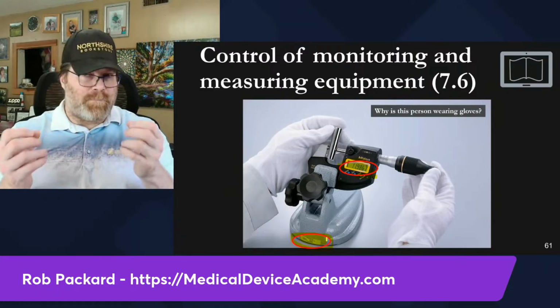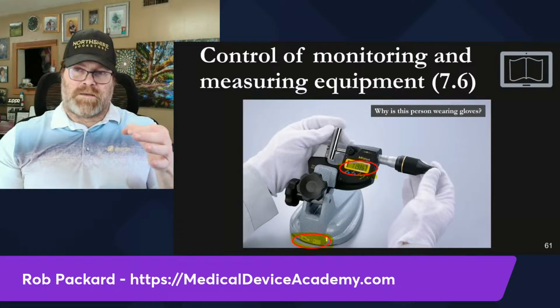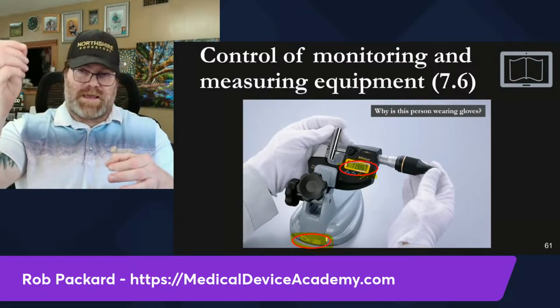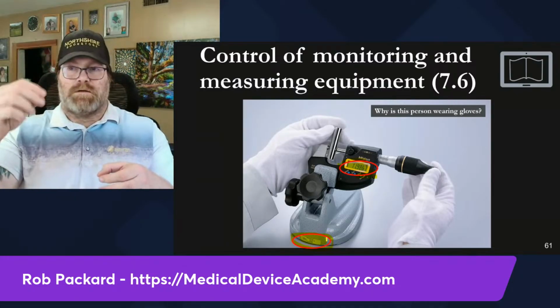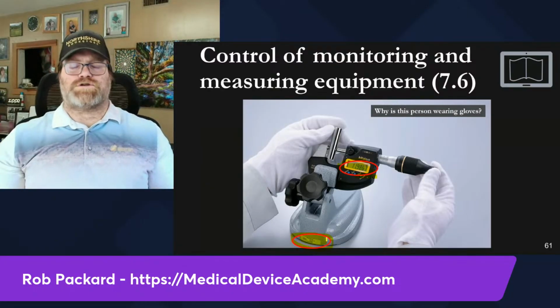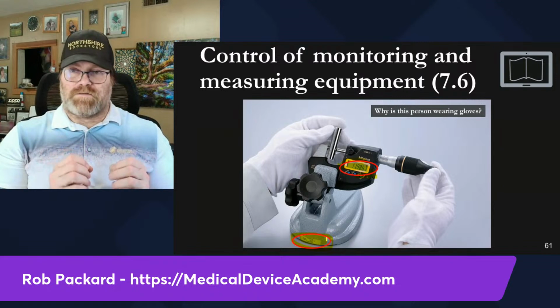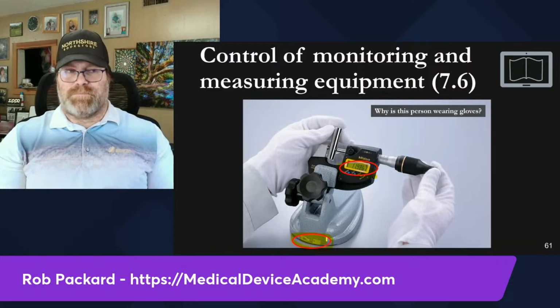And you might not remember that from 6th grade, but the science teacher had a ring and he put a ball through it, and then he heated it up and the ball wouldn't go through the ring anymore because it grew. That's what we're talking about here. Temperature matters to the size of something. So when you have tight tolerances that you're trying to measure, the temperature and humidity matter. So you need to make sure you look at that.